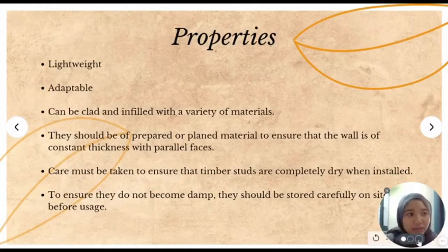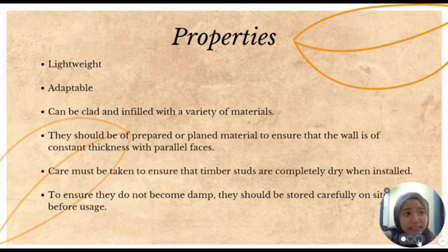Okay, what are the properties of the wood stud? Okay, so timber studs are easy to use as they are lightweight and adaptable, and they can also be clad and infilled with a variety of materials to give different finishes and properties. Also, they should be planed material to ensure that the wall is of constant thickness with parallel faces, and care must be taken to ensure that timber studs are completely dry when installed. Otherwise, they may be prone to shrinking and twisting as they dry out. Lastly, to ensure they do not become damp, they should be stored carefully on site before usage.